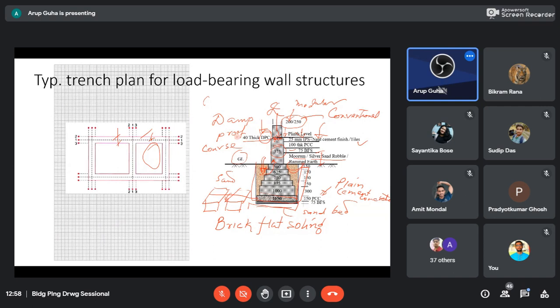That could be a very rich mix of mortar without stones, or it could be plain cement concrete, and you can add certain water resistant admixtures to it. You can add some protective membranes like plastics. Those prevent travel of moisture from the lower level to the upper level, to cut off the dampness in your buildings, rooms.